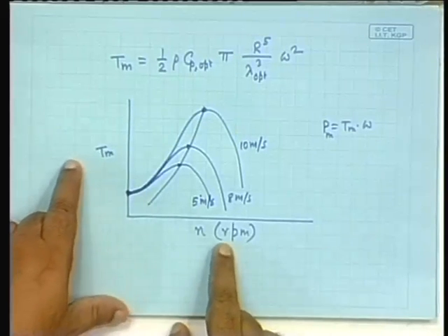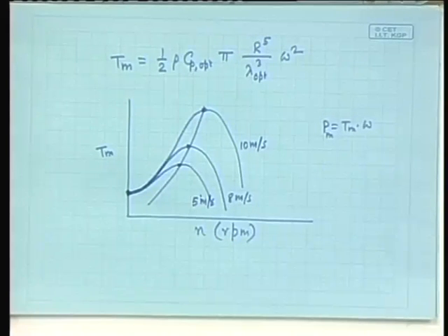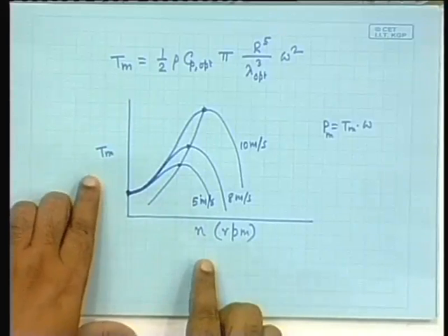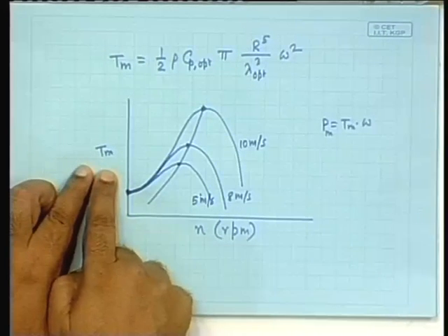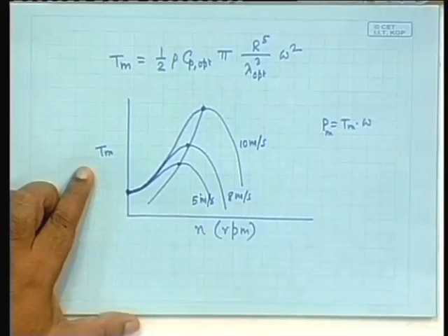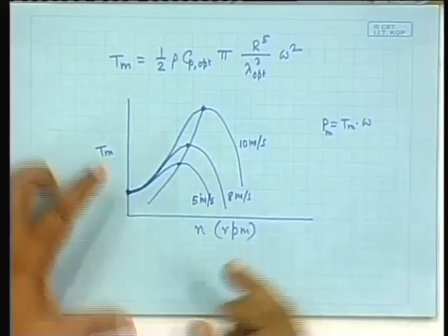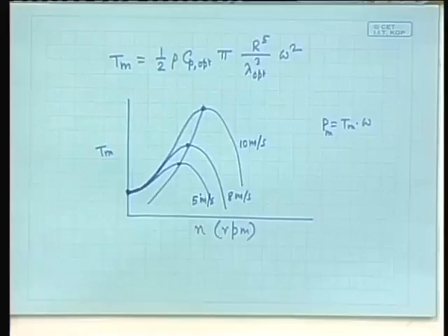Now, why do we need to understand this? Because this is the aerodynamic torque produced. That means the wind is producing this torque, but when it rotates, when you are extracting power from it, there is a back torque, right. When you are extracting power by converting to electrical energy, that conversion to electrical energy gives a back torque to it. So, ultimately when the forward torque and the back torque are the same, then that will be the equilibrium condition.